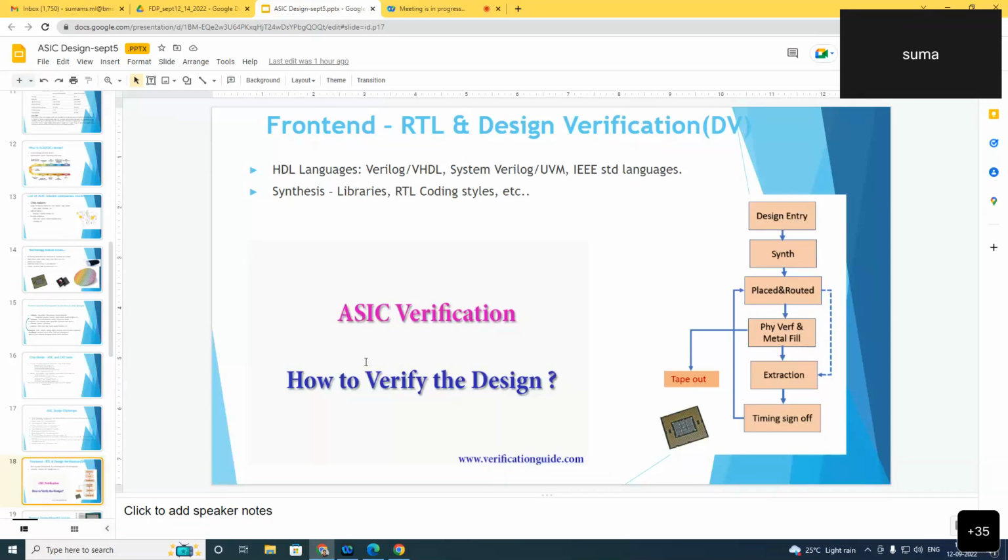And we have the technology files, where the libraries consist broadly of standard cells and environmental variables, and also the library level attributes. For example, the time unit, the voltage unit, the capacitive load unit. These are the attributes defined in the library to model the variation in the environment, which consists of three parameters: PVT, the process, voltage, and temperature.